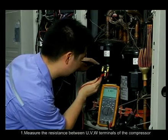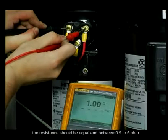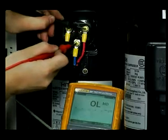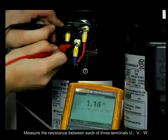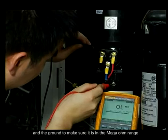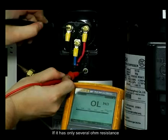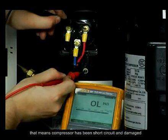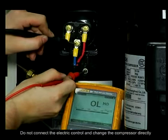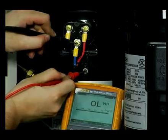1. Measure the resistance between U, V, W terminals of the compressor. The resistance should be between 0.9 and 5 ohm. Measure the resistance between each of the 3 terminals, U, V, W, and the ground to make sure it is in the mega ohm range. If it has only several ohms of resistance, that means the compressor has been short-circuited and damaged. Do not connect the electrical control and change the compressor directly. If it is normal, please go to the next step.